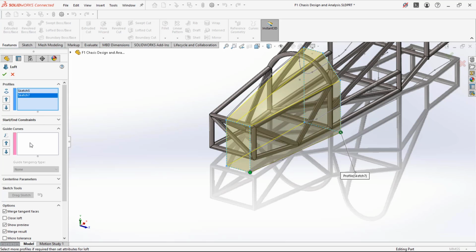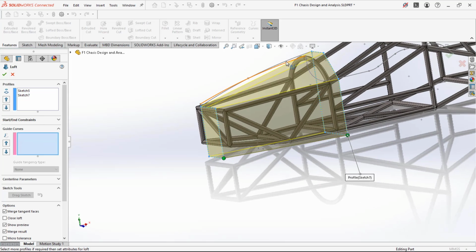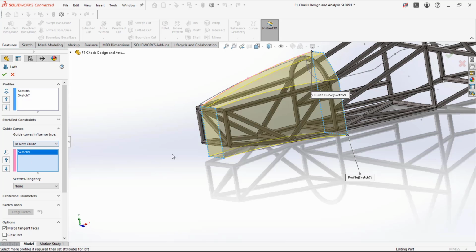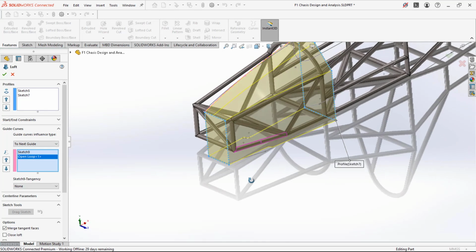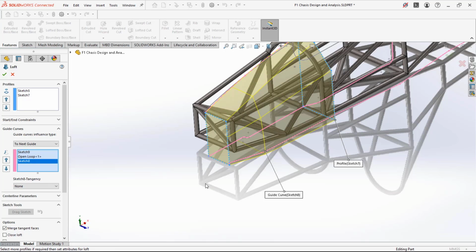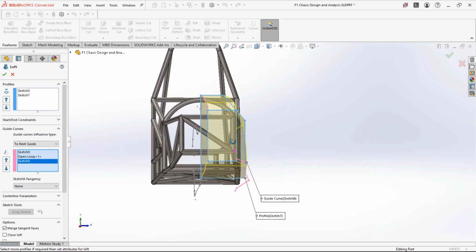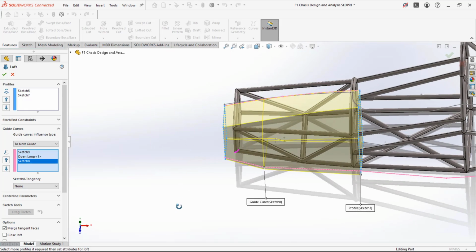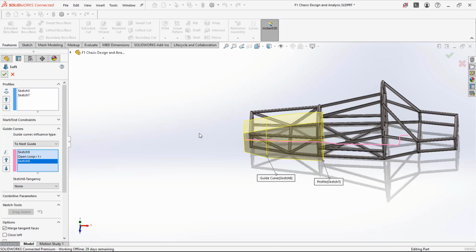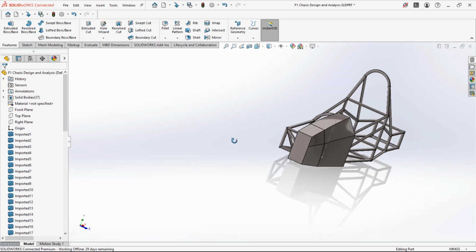Now you can refer to these profiles and the guidelines by using the loft tool. This line, green check, as you could see. I had taken 3 guide curves as a reference, and this is fine, no issues. Green check. You can mirror it later.